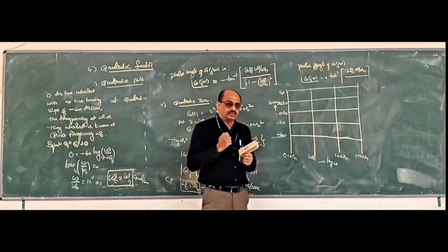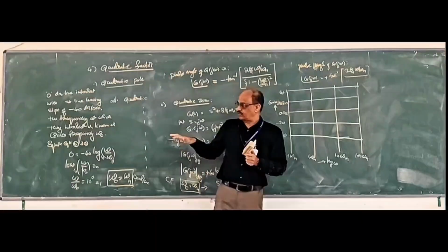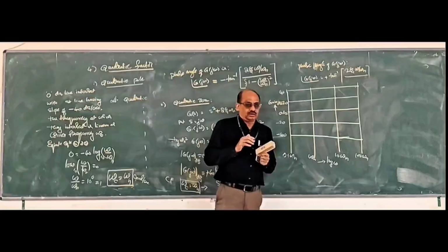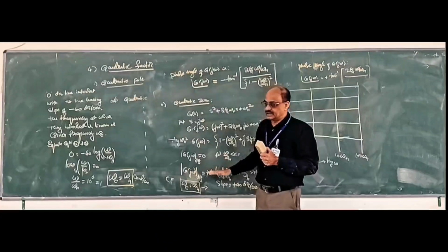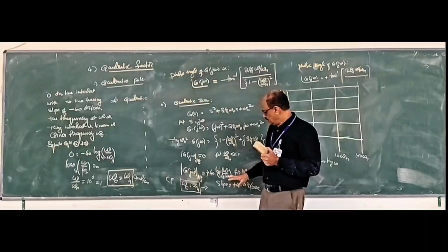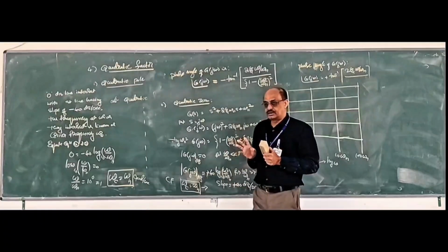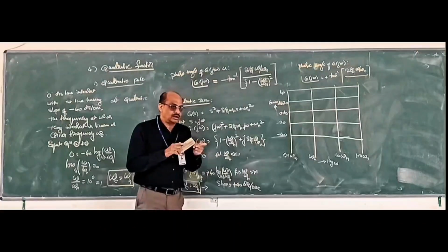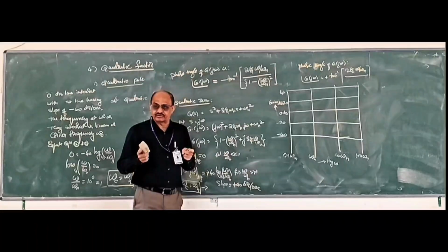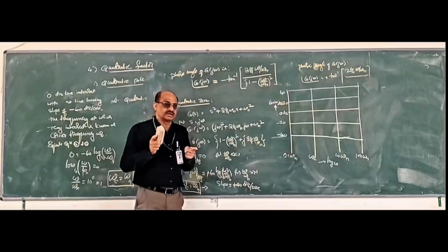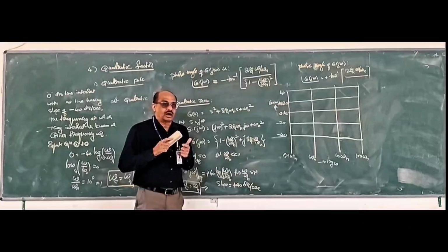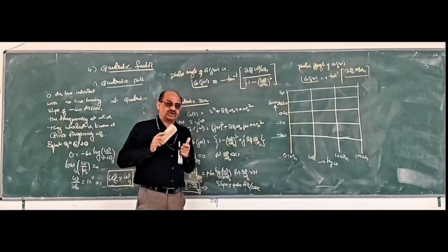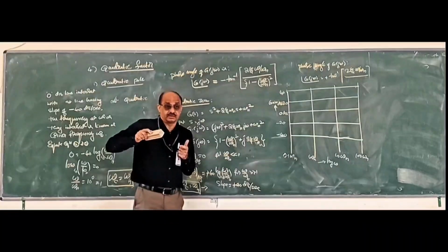Now it is time to sketch whatever we got with respect to quadratic. It is very simple. Whatever analysis we have done so far, you need to remember that ultimately a quadratic pole has a 0 dB line till the corner frequency omega c equal to omega n, and later it has a straight line with a slope of minus 40 dB per decade.